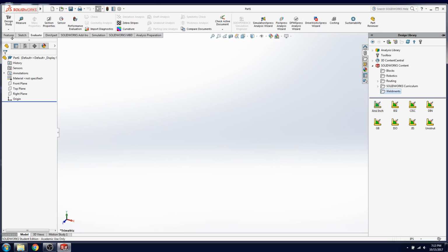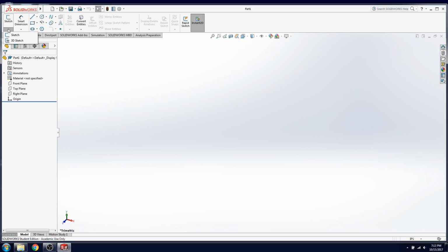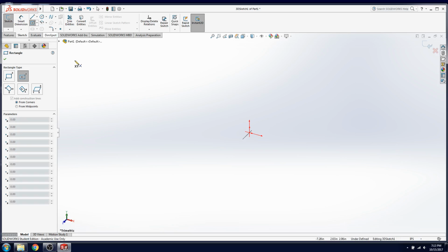properly, I hope. Now let's create sketch, and this time when we go to sketch, we'll create 3D sketch, and I'll just throw few lines, just to make sure that our sections are working properly. So this is rectangle. I will do that on a top plane. In case of 3D sketch, anytime we want to work on a certain plane, we need to use tab to change position.